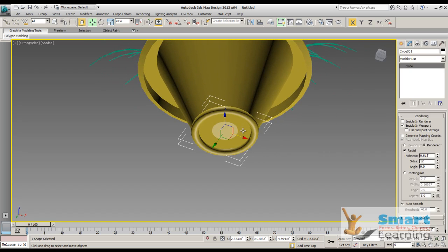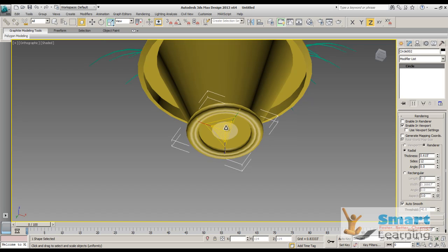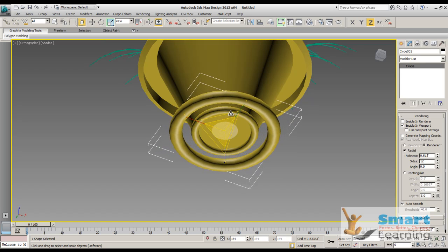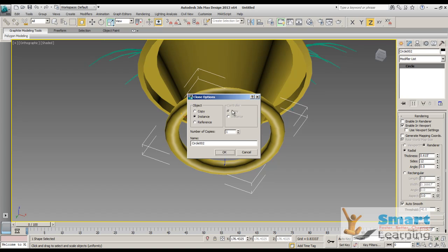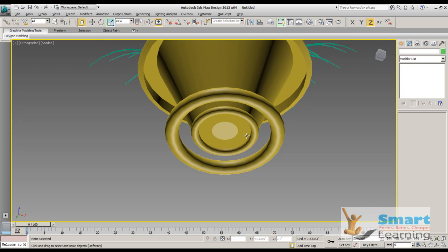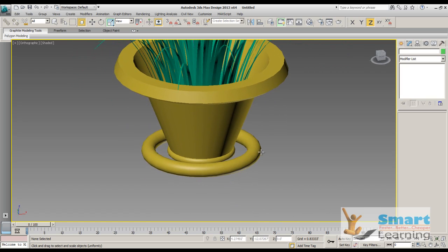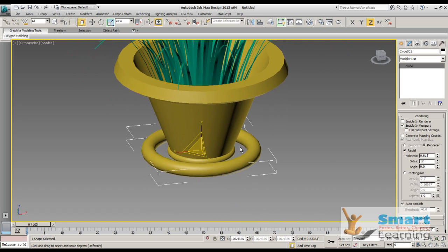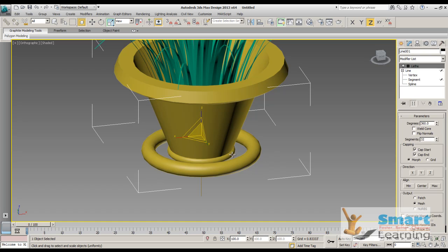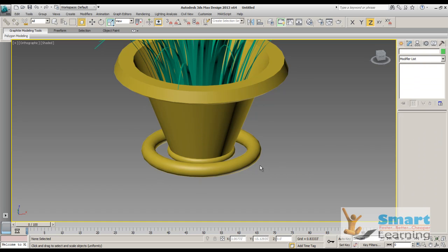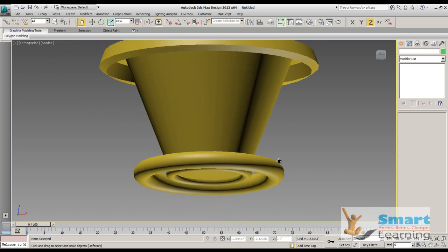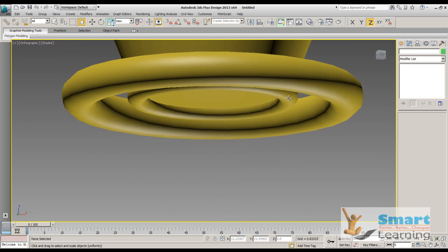Once the radial thickness is done, you can scale this object. To select this, go to Scale, press the Shift button, and another one will be created with respect to the same center. Release it and go for copy. Now select this, and whatever dimensions you have selected for the inside circle, you have to put them here.